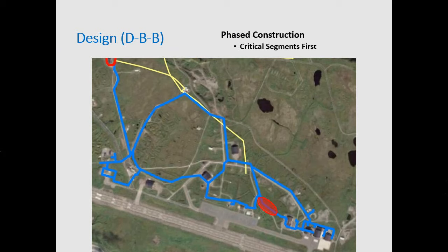So now the design bid build. I took that screen grab. The blue line is our design bid build, about 29,000 feet when it was all said and done. The most critical section: right now the system is offering about 20 PSI of pressure down here due to leaks and valving, even though this is higher in elevation than here, but their system is failing.